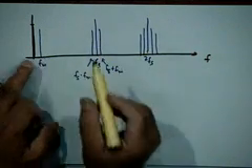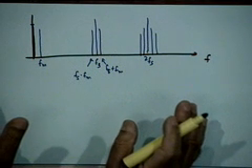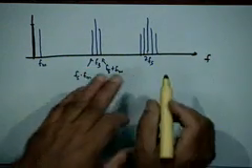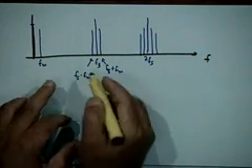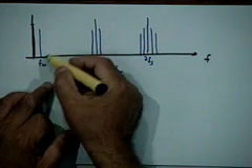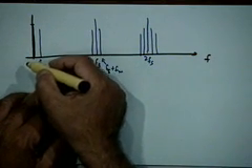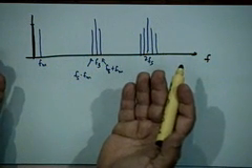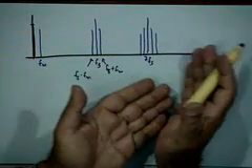However, the interesting fact, and the useful fact, is that as far as the baseband part is concerned, it contains only a DC component and the desired signal component, right? So what kind of spectrum you have around fs and 2 fs is not very important, as long as my baseband signal is intact. So to recover the baseband signal, what should I do? Again, just put a low pass filter, because all these signals will simply disappear once again.